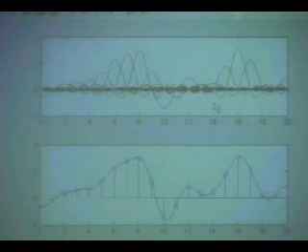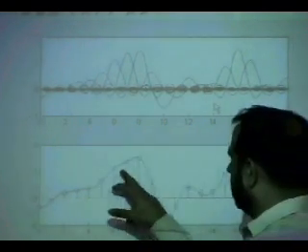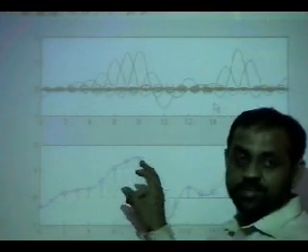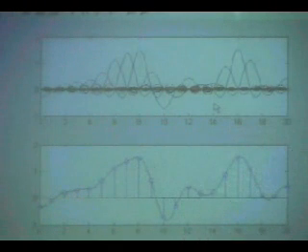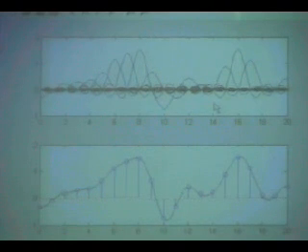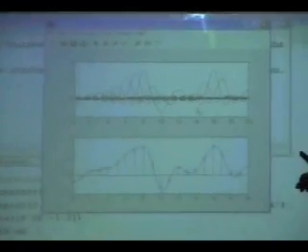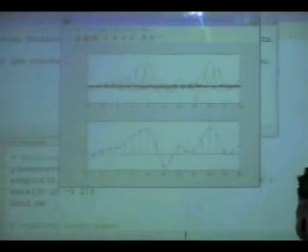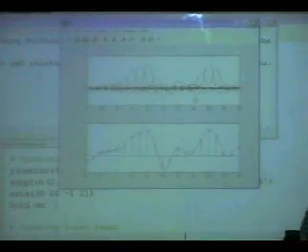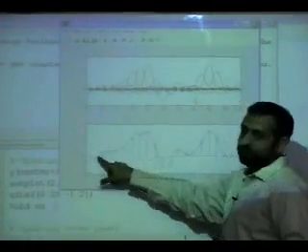So this is how you reconstruct. Interpolation is happening, but this is called an ideal interpolation. A sinc is an ideal interpolator, but obviously a sinc is not possible in that sense. So you have to pass it through a low pass filter, in the analog domain. It'll be something like this, and it will help you reconstruct whatever you have thrown away.